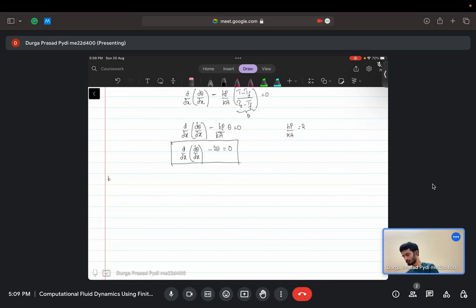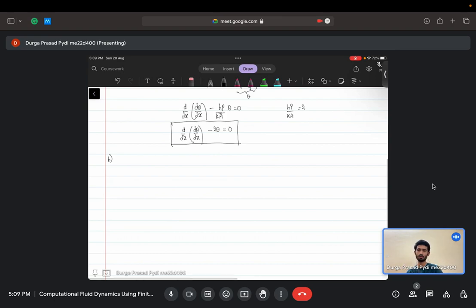So the next step is essentially to use the finite volume method to discretize this on our domain. The discretization can be done in two different ways. We have a domain of x equals 0 to x equals 1. The first way of discretizing is we fix the nodal points. We fix x equal to 0, and then we choose these points, and then we draw the control faces or control surfaces, at exactly half of these nodal points.